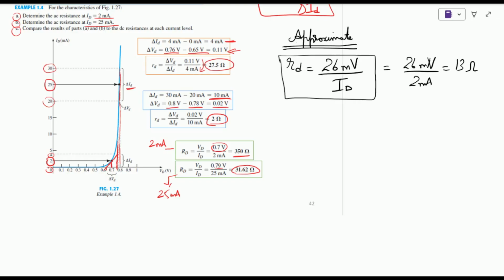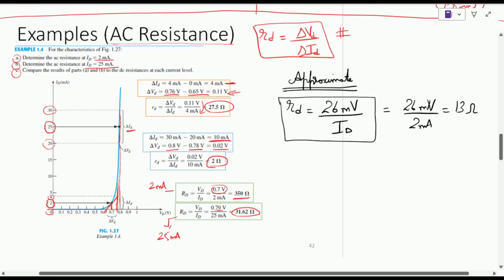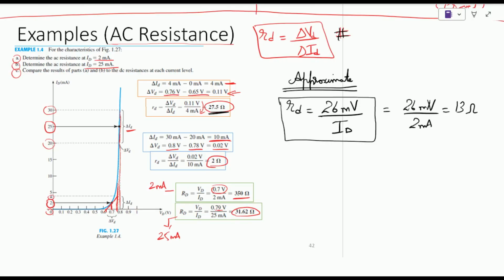30 ohm. Okay, so now we can see that it is not exactly equal to what we found in the example using the first equation, which was this. So in our first case, the resistance was 27.5 ohms, and if any equation is approximate, its values should be near or closer to it. So how can we bring it closer? Keep in mind, another important factor is the value of eta, which in the Shockley equation is known as the ideality factor. Normally this ideality factor is provided by the vendor and its value is between 1 and 2, but normally we take either value 1 or 2.